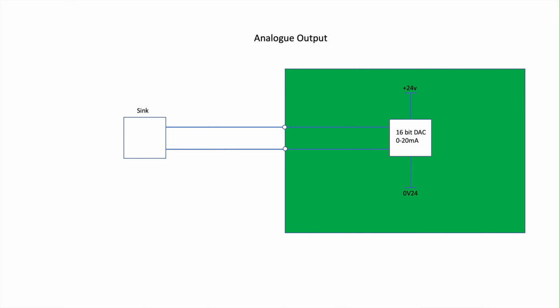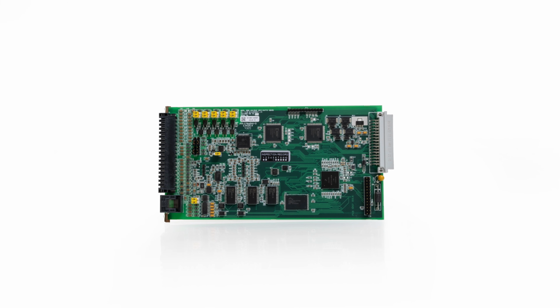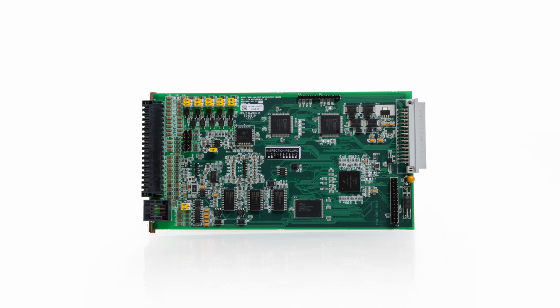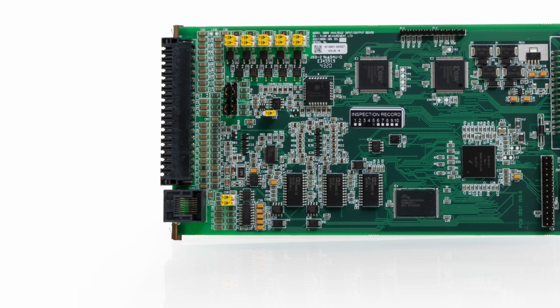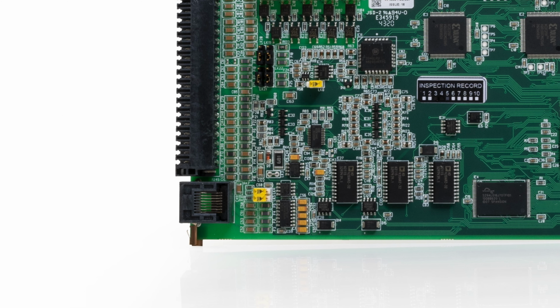The analog outputs are selectable as either 0 to 20 mA or 4 to 20 mA with a 16-bit resolution. The maximum loop resistance is 750 ohms. It should be noted the I/O boards have a single non-isolated serial port with RS485 and RS232. These are mostly intended for connection to meters via a barrier module, but can be used for most functions.